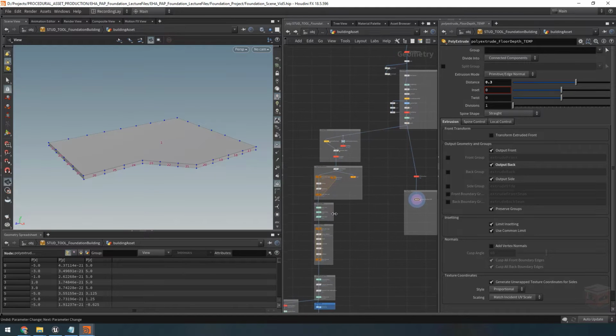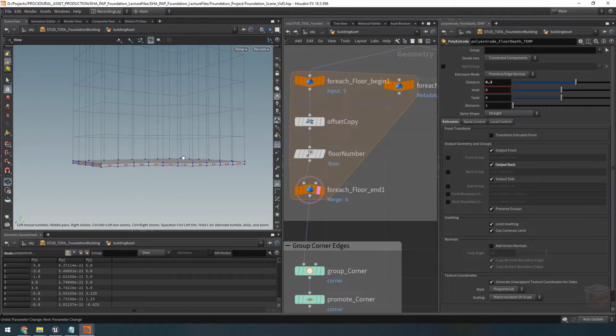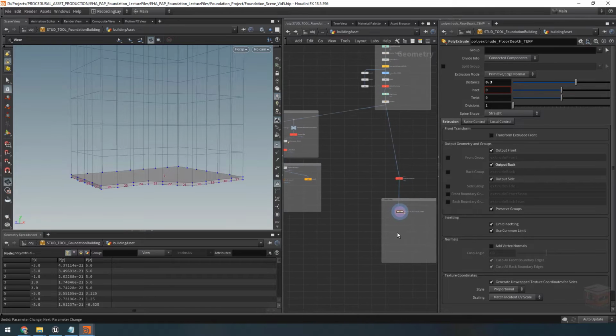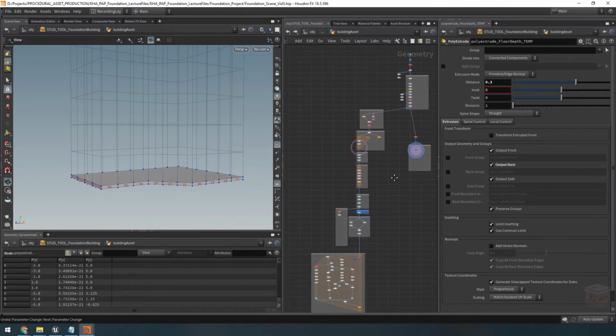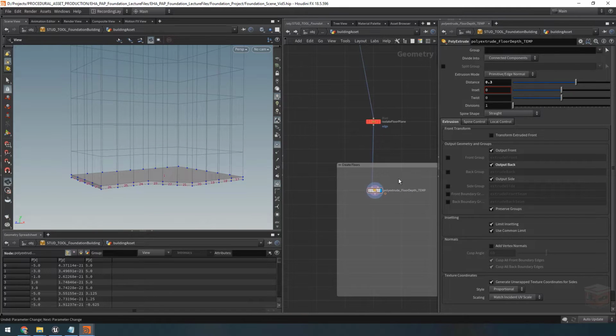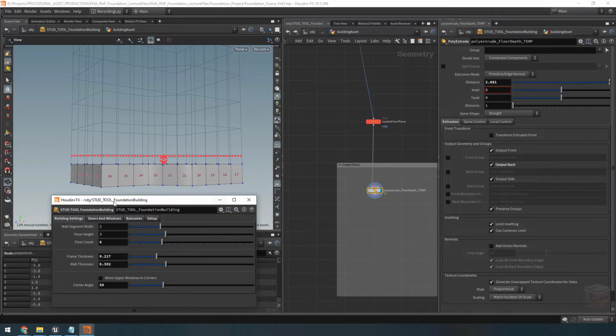And there's one other thing you need to know before we continue, and that is that this floor that we're adding right now, this layer, is going to sit in between the tiles of our building. And it's going to eat away at the available space in our building. But you do need to remember that if you make your floors too thick, like so, then as they get copied up the building, there simply won't be any space left. So in that case, you would have to go to the floor height and increase that one too.